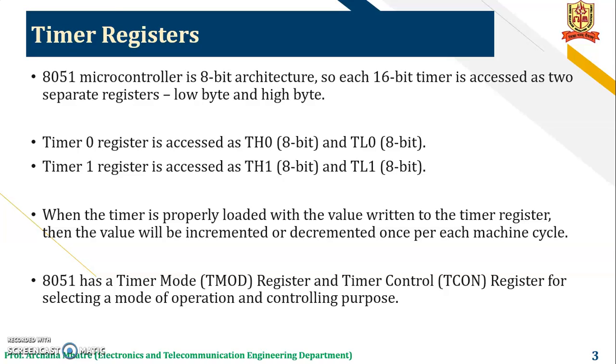When the timer is properly loaded with the value written to the timer register, then the value will be incremented or decremented once per each machine cycle. 8051 has the timer mode TMOD register and the timer control TCON register for selecting the mode of operation and controlling purposes.